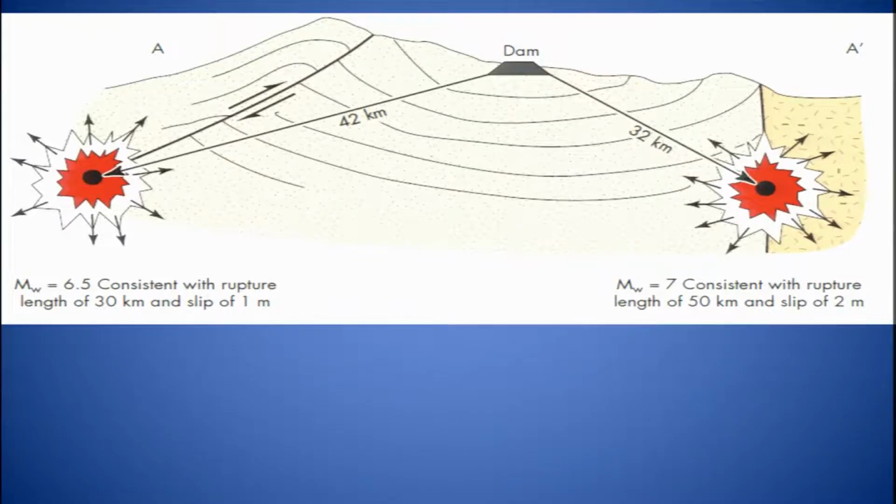So, the most important part which we would like to understand is where the source of the earthquake is: one is the fault where it is exposed on the surface, and second is at what depth the earthquake will occur and how far we are sitting from the earthquake.